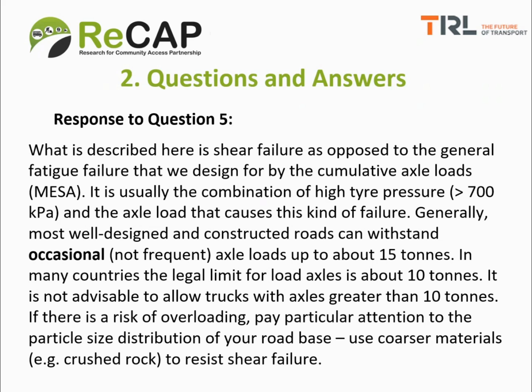If there is a risk of overloading, you should pay particular attention to the particle size distribution of your road base, and you may be required to use coarser materials such as crushed rock to resist shear failure. But of course, crushed rock is quite expensive for low volume rural roads.